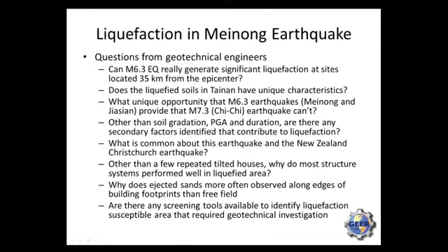Other than PGA and duration, is there any important secondary factor that contributes to liquefaction? The answer is no. And yes, the yes part meaning that we shouldn't characterize liquefaction sites based on geological description only. We found out a lot of man-made fill caused liquefaction. What is common about this earthquake and the New Zealand Christchurch earthquake? One important thing is the myth that geotechnical engineers think that earthquakes can densify material, such that it will not liquefy in the future. It ain't true. Now, we have repeat liquefaction at the sites.